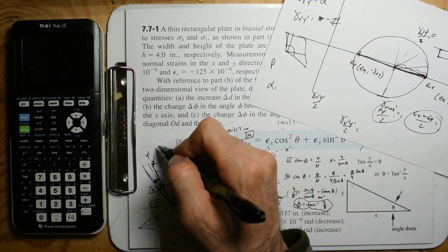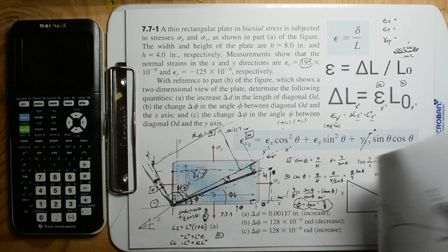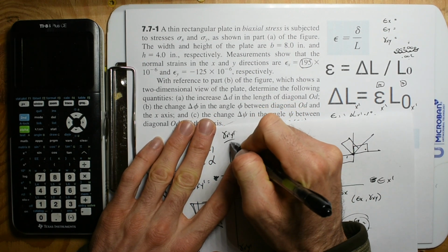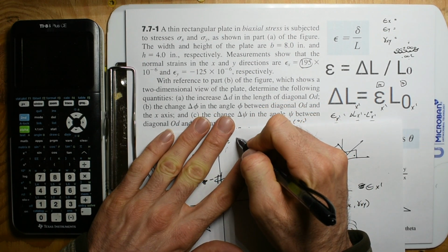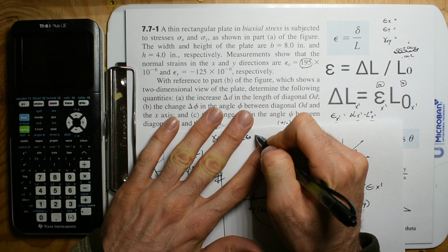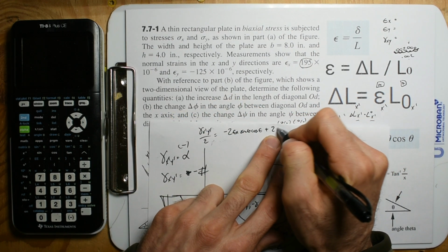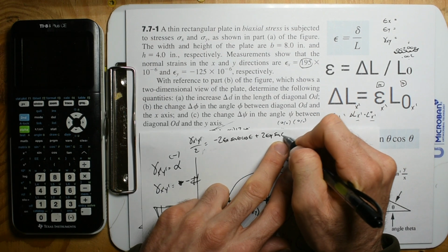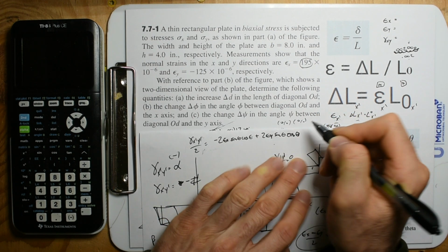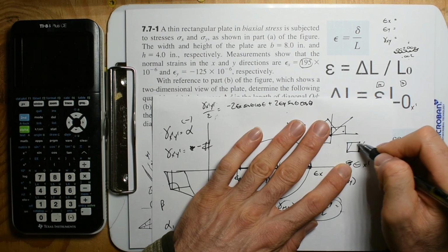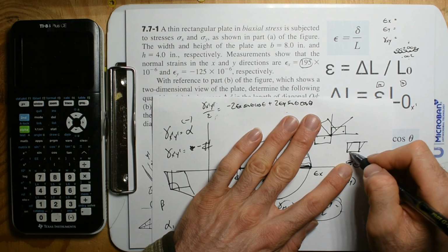And yeah, it's proportional to the strain. You know what I mean? I kind of have that equation from memory. x1, y1 divided by 2 is going to be negative 2 εx sine theta cosine theta plus 2 strain in the y sine theta cosine theta. Now we can say that if this is my initial thing and I do that,